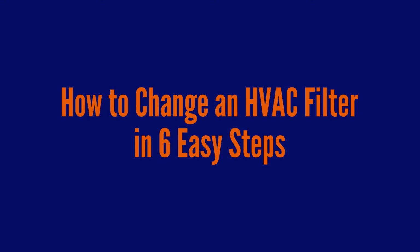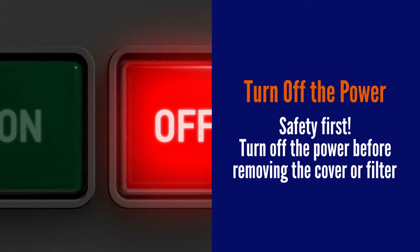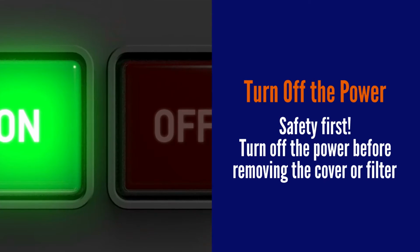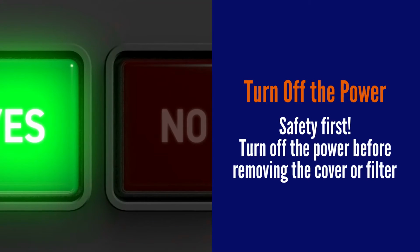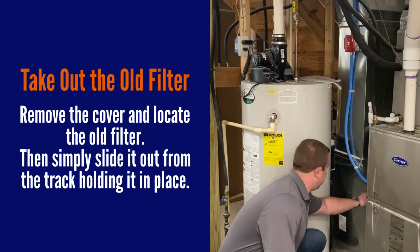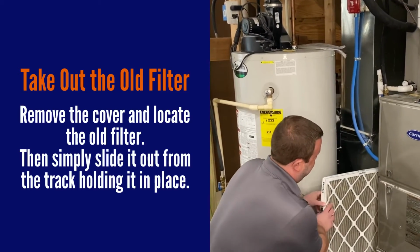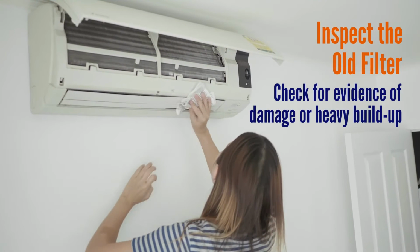The basic process for changing an HVAC filter can be broken down into a few easy steps. Safety first. So step 1 is to turn off the power before removing the cover and filter. This will keep you from mistakenly touching any moving parts or live wires. Step number 2 is to remove the cover if needed and locate the old filter. Then simply slide it out from the track, holding it in place.